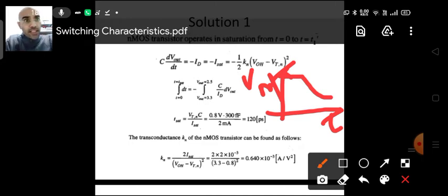So we have to find that up to certain voltage. This is what the case is, so it is falling. You see, this NMOS transistor will operate up to some point in one region and after that point in another region. So how to find out in which region it is operating? Just to find that, we have to use our conditions of the drain, the linear and saturation regions.